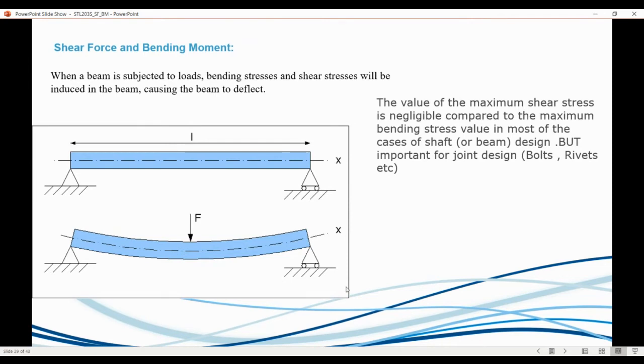But if you take a very short beam, maybe a small ruler, for instance, you support it on the table, you clamp it with one hand on the table, and you try to actually bend the beam. It doesn't fail by bending, but it'll completely shear off. So for shorter beams, shear failure is more predominant; in longer beams, it's bending. Of course, bending is the most important thing when looking at beams anyway, before you're designing beams.